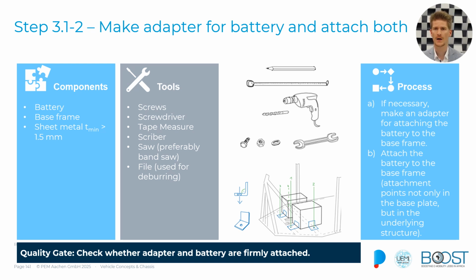And again, we make a template, and then we will cut out the sheet metal needed. The sheet metal is then folded into the right angle that we want to have. With a punch, you show the position of the sheet metal brackets on the base frame. You drill through both the bracket and the base frame, and then it is secured via nuts and bolts. And via that, you can adapt to any kind of size of your battery, and you can also adapt to the capacity needs based on your use cases.